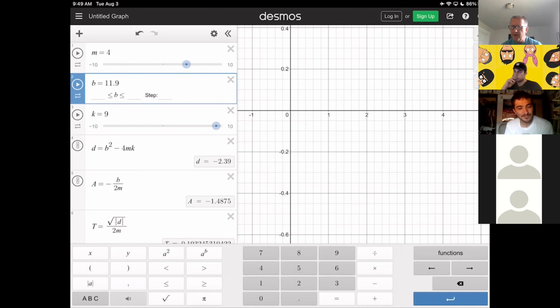So the idea is if you changed the damping, if you damped it a little less, then it's now going to have the strength to oscillate a little bit. So it would have made it, if you will, below the x-axis. It wouldn't have just gone from 0.3 and worked its way as quickly as possible to 0. It would have started at 0.3 and got underneath the axis a little bit and oscillated a hair. Now it still would have leveled out really fast. Does that make sense? But it would have actually made it past 0 and then come back to it. That's why it's critical. It's like the line between oscillation and not oscillation. Is that kind of neat? Doesn't that sort of make physical sense to you if you think about it? That's kind of cool, right? That is cool.